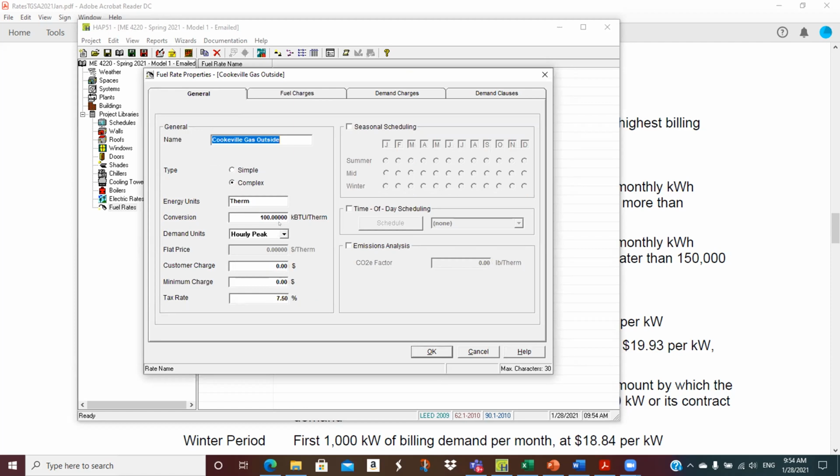Okay, is the unit. So you may not be familiar with therms. A therm is 100,000 BTUs of energy. When you look on the bill, it says CCF. The first C stands for 100, the Roman numeral, and then the CF is cubic feet. So 1 cubic foot of gas is, nominally speaking, 1,000 BTUs. So 100 cubic feet is 100,000 BTUs. So these units are essentially the same.